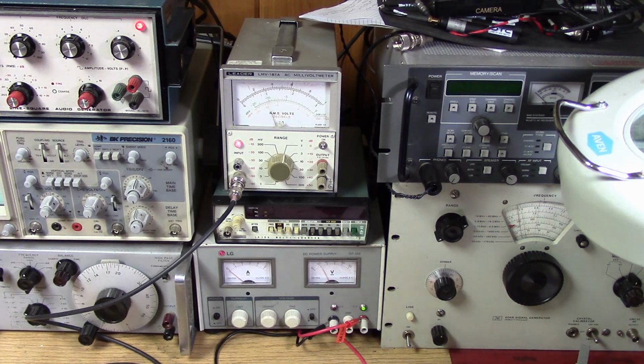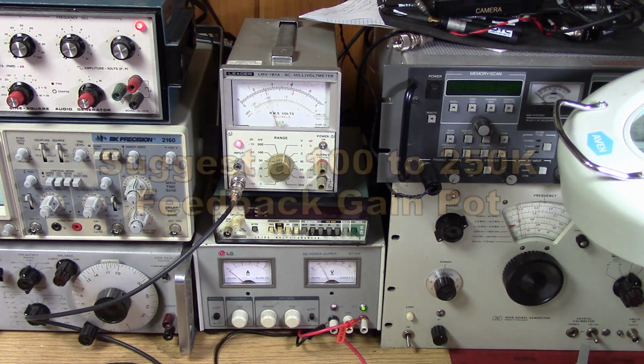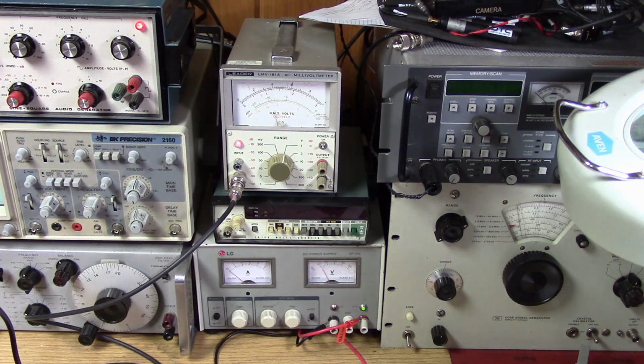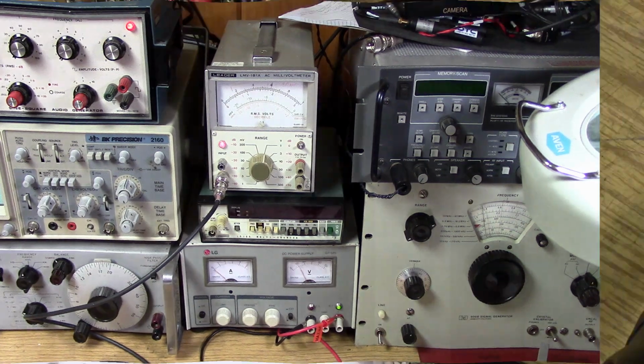And of course we have that output control on the schematic that will allow us to adjust this down accordingly. Now if it turns out that it's gross and it's way too high, we can change that feedback resistor on the 741 to something smaller, like a 39K or a 47K, to cut the gain down. But good estimate on the electret microphone. We now have our microphone amplifier and it is working.